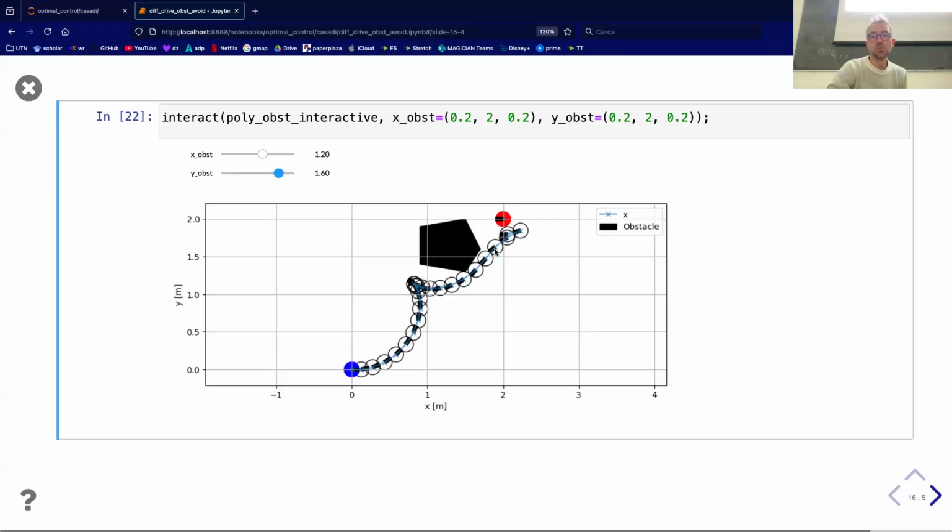And it's almost impossible to reach this configuration if you start moving backward from this state here, because the robot needs to end with this orientation pointing on the left. So I would say that here we should provide an initial guess which makes the robot move forward and then turn left so that it reaches the final state from the right rather than from the left.